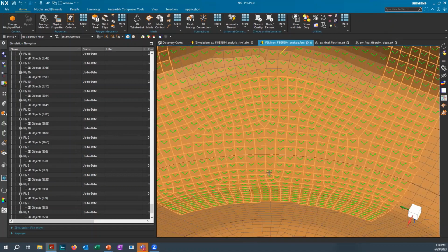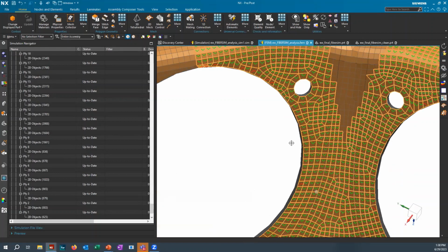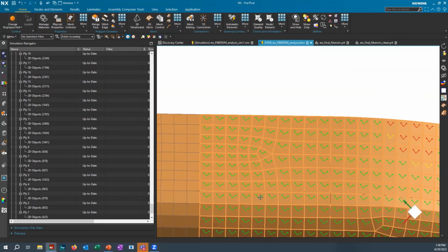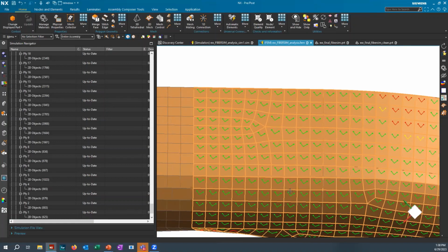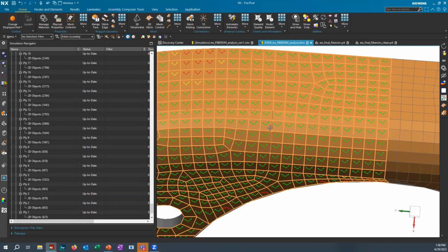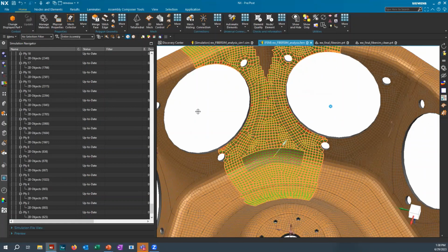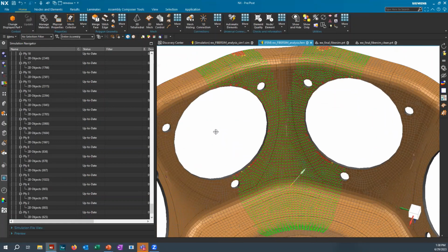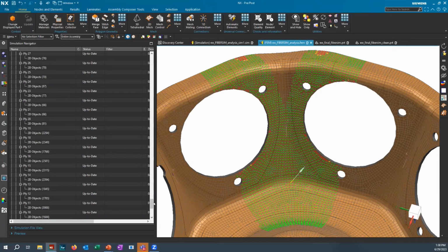We can see how here we're matching relatively close to the 45-degree angle. But when we come up here, this is probably closer to 40 or even 30 degrees, just because of how this part was laid up across this piece. So now we're actually capturing that data in the model as opposed to not capturing it and assuming that the analysis model is the correct way only.